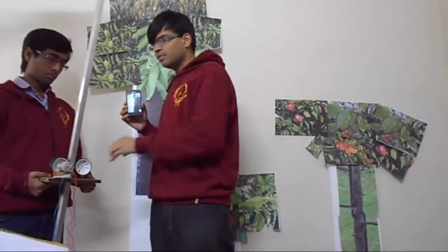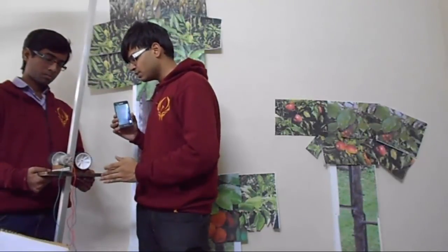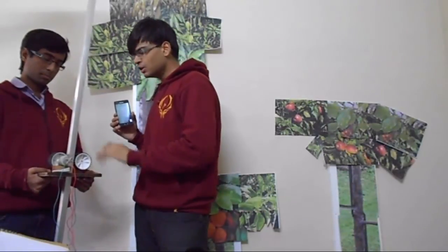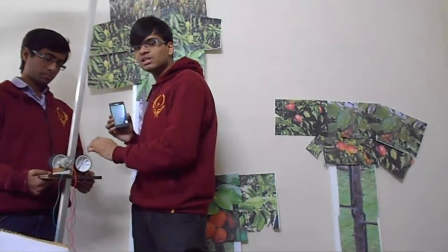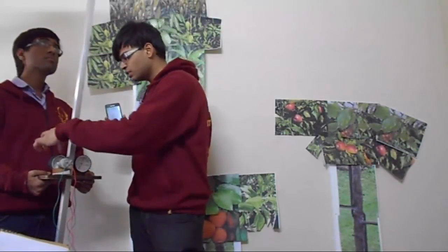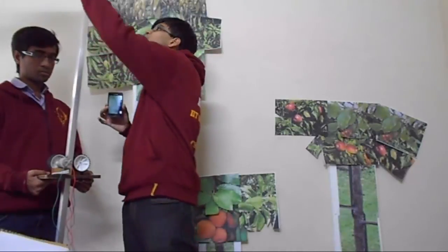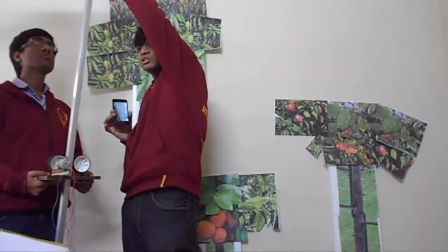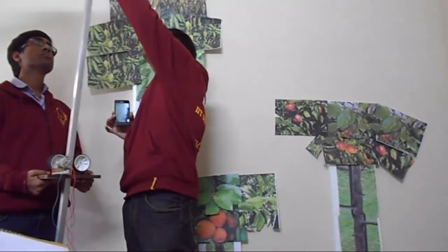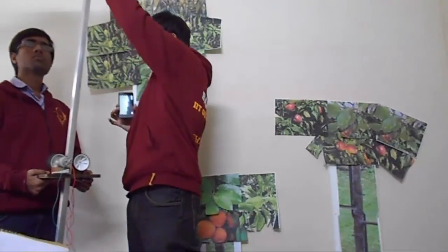This is our hardware. The hardware consists of a rectangular board 21.5 cm in length and 15.5 cm in breadth. Two motors are used for vertical transmission of the nozzle system. Both motors are high torque 10 RPM motors with rubber wheels 1.5 inches in width. Three pipes are attached to the nozzle system, and they are used for pumping the requisite amount of pesticide.